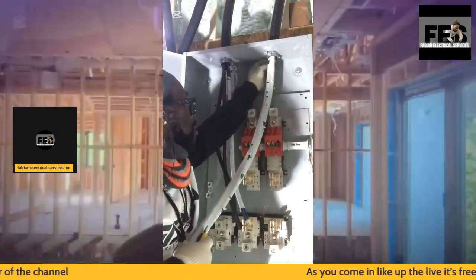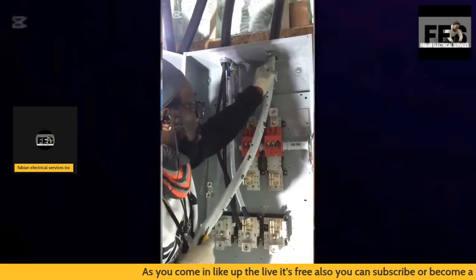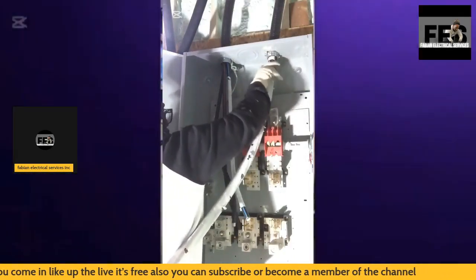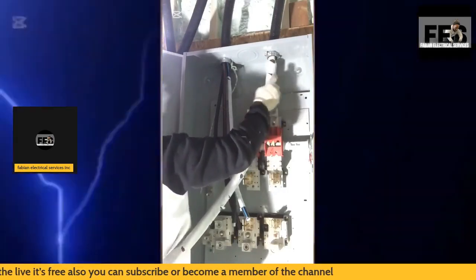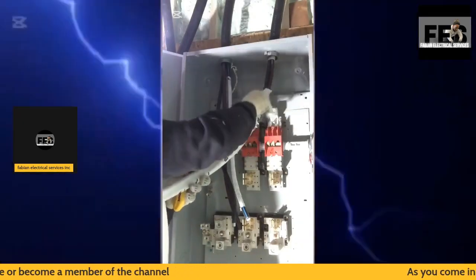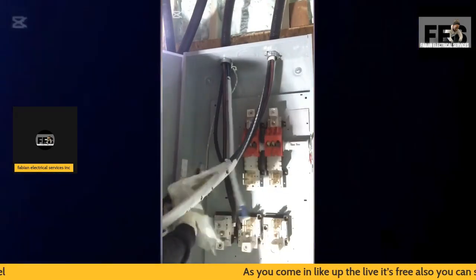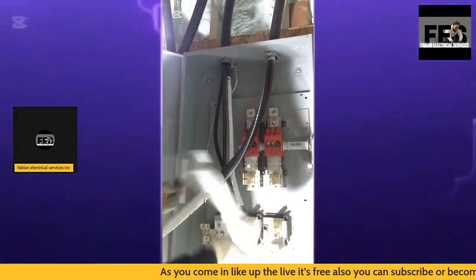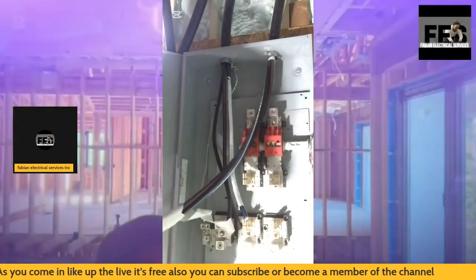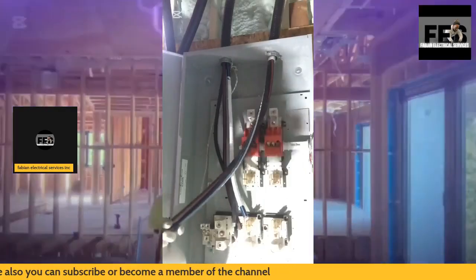But when it comes to any electrical installation that's more than 5 feet away from the actual electrical disconnect that's located outside of the home, it has to have a means of disconnect. So the main electrical 400 amp panel is located inside of the electrical room, inside of the basement of the home, and it's more than 40 feet away from the meter base.